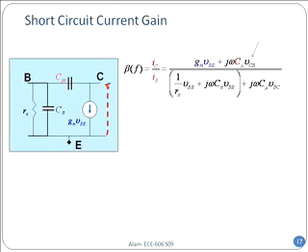IC over IB. Look at IC first. IC has these two current components, right? When the current is coming in, one is this current source going down, gm VB. That's one piece. And another is flowing through the capacitances. What is that? Capacitance impedance j omega C multiplied by the voltage difference, which is the collector to base voltage difference. Do you see on the numerator I have VCB multiplied by C mu. So that's what I have on the numerator.